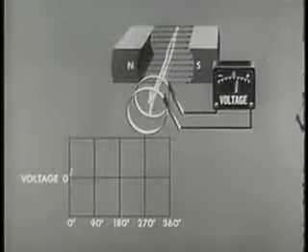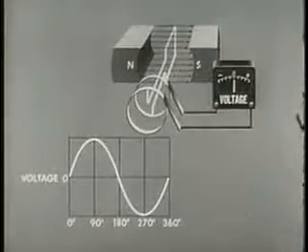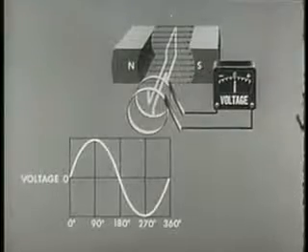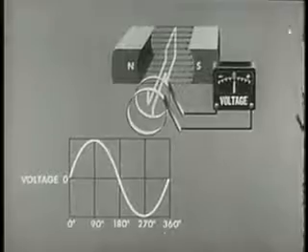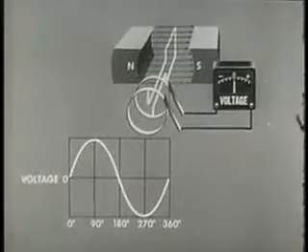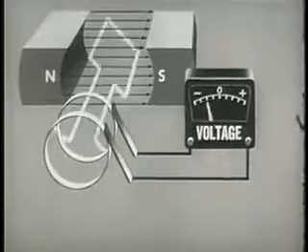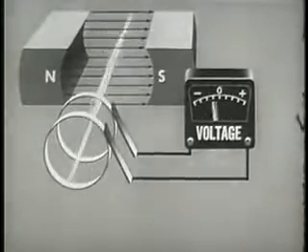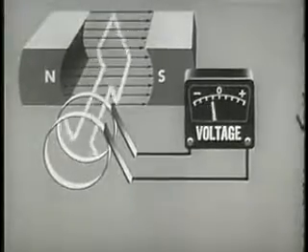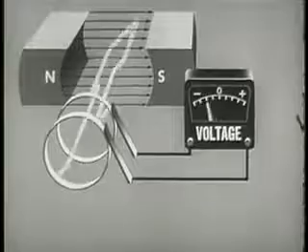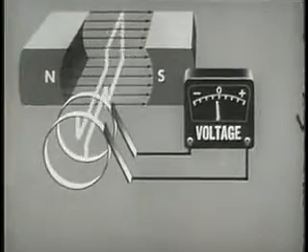This capability is responsible for the development of radio communication. All generators produce AC internally. In this basic AC generator, the arms of the loop cut lines of force in opposite directions, causing electromotive force of opposite polarity to be generated in the conductor. To maintain the AC character of the output in this generator, we use slip rings instead of the commutator segments used in the DC generator. This use of slip rings is the only structural difference between AC and DC generators.